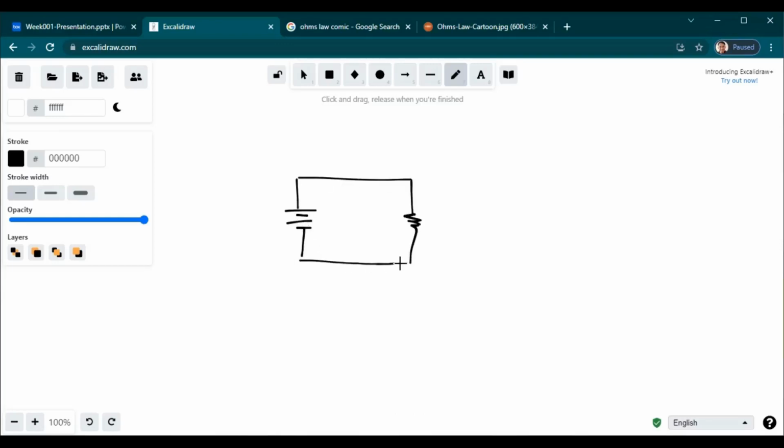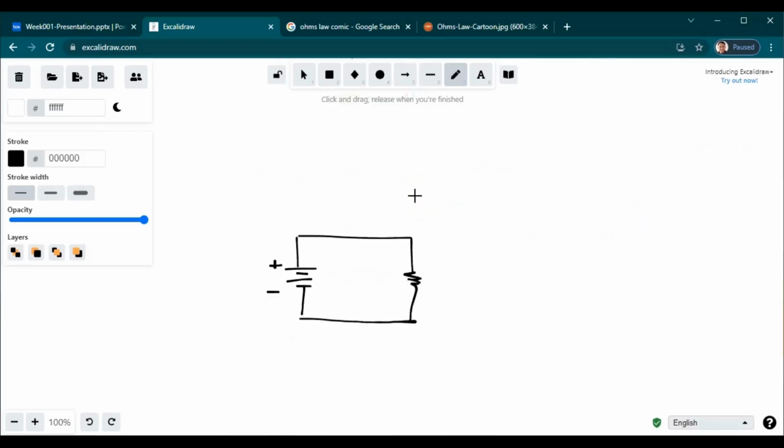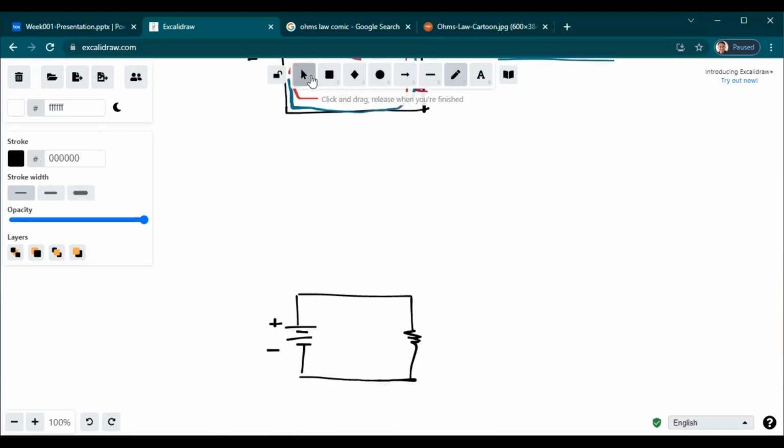This is just an overview. We will not go really deep into that. But again, recall that the current is flowing around the circuit while the voltage is only present on the components. So if we are to measure current, we use an ammeter. Okay, the ammeter is the equipment being used to measure the current. So when we measure current, we connect it in series with the circuit so that the current can pass through the ammeter since it is measuring current.